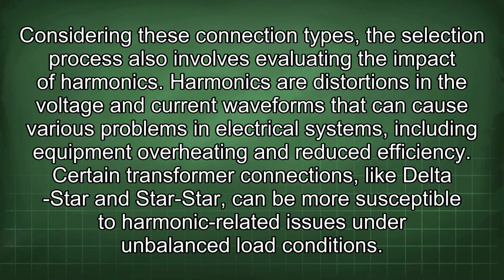Considering these connection types, the selection process also involves evaluating the impact of harmonics. Harmonics are distortions in the voltage and current waveforms that can cause various problems in electrical systems, including equipment overheating and reduced efficiency.